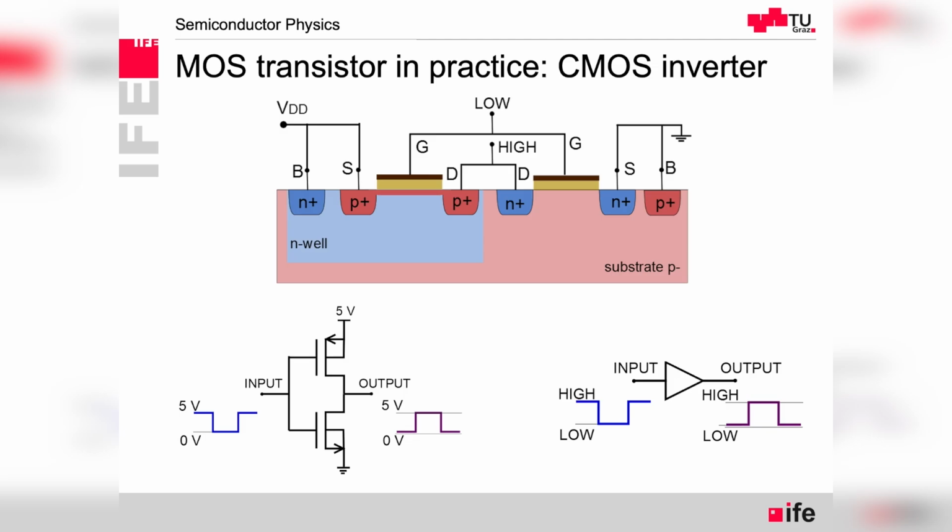When we have a large width of the transistor, then it's much more powerful in terms of leakage current. Because if a small transistor has leakage current, a 10 times bigger transistor will have 10 times higher leakage current. And the leakage current, what you can see in these characteristics, the purple line, which is the sampled signal, it's discharging during the holding time. And that's because of the leakage current in our transmission gate.